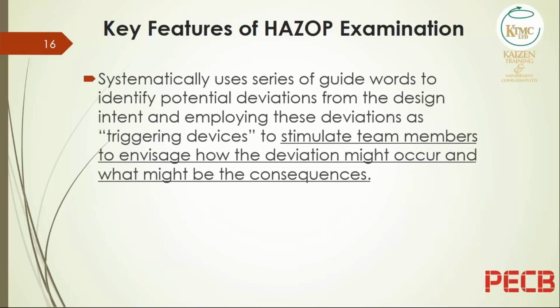Key features of the HAZOP examination. It is a systematic approach. So we use the guide words to identify potential deviations from design, and we go throughout the process from beginning to end. We look at various nodes, and we consider how to get the information from the people involved.